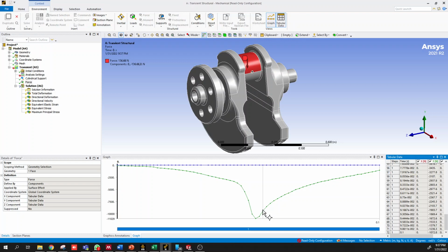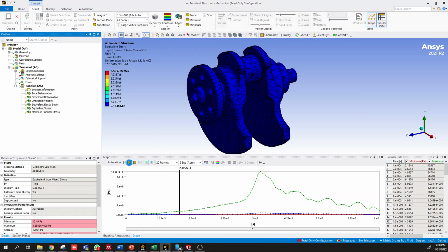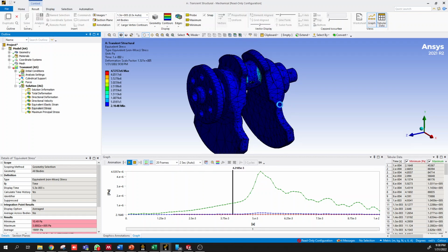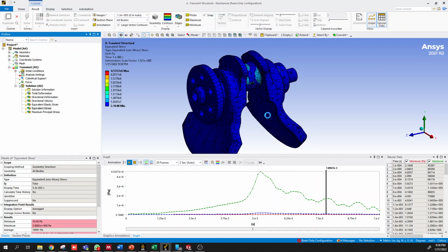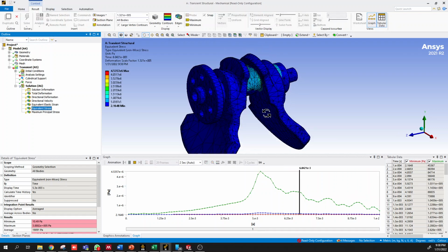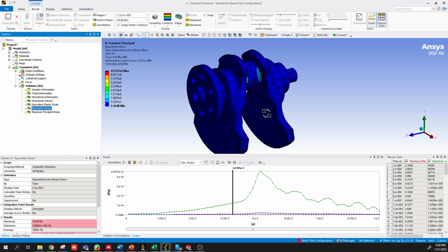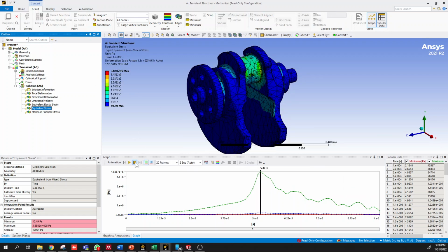So that stress propagates through the actual component here differently, because now you can see the crankshaft cheeks here, it's almost as if we're shocking it. This is what happens when we shock it. It's ringing because we're hitting it so hard. So this isn't a physical result. Obviously, this isn't what you'd expect to happen. This is just an artifact of the way that we're simulating it and